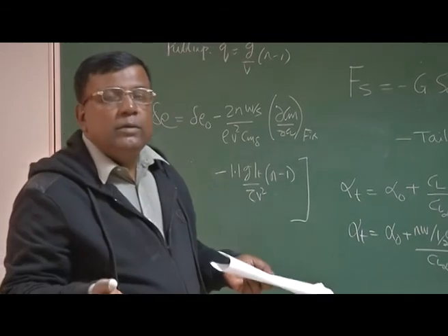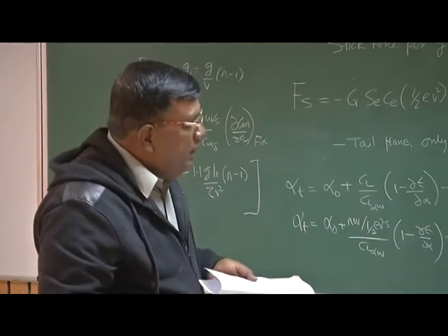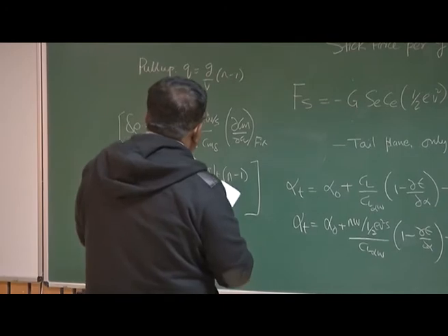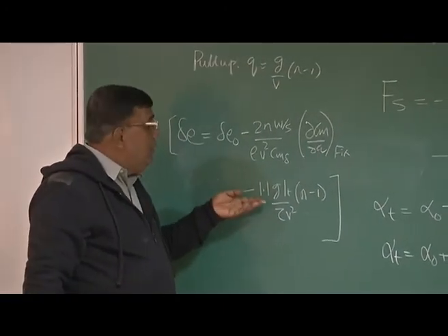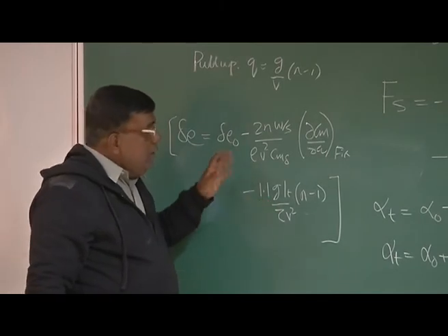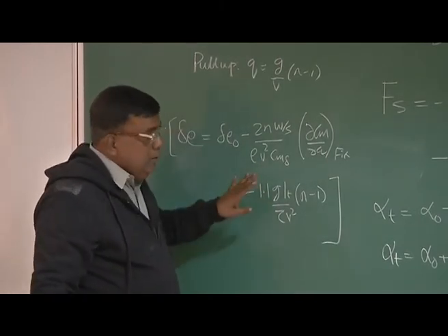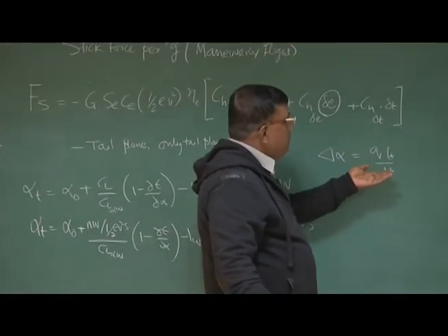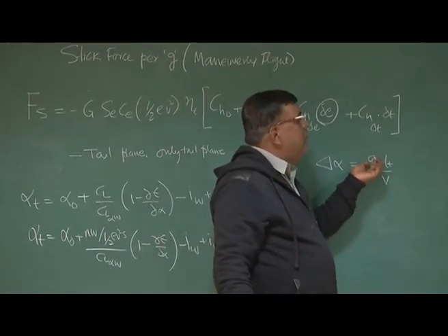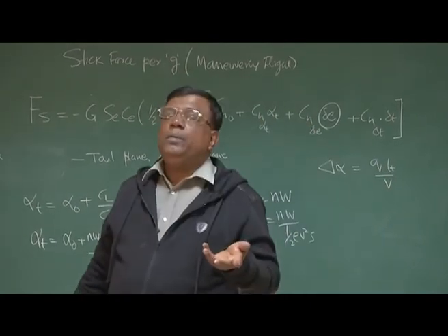So they also add some sort of stability, and we have to take care of that effect by elevator. That is why the 10% increment was there to counter the fuselage effect, right, from the delta E perspective. But as far as alpha tail is concerned, it is only increased by this much value, where Q has to be put equal to Q pull-up or Q turn.